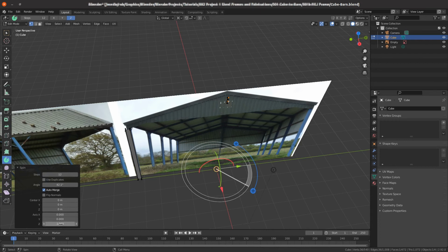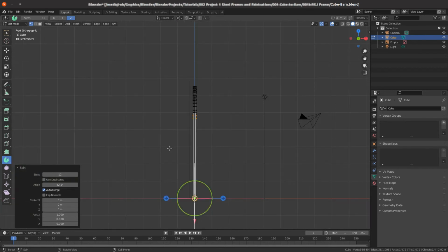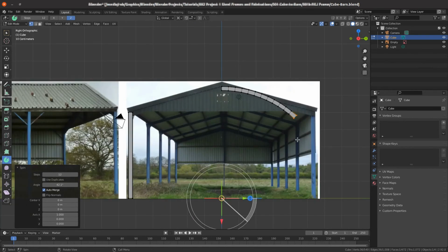At the moment Z is set as 1, so that takes all of the rotation, and we want X to be set to 1, so we'll set that to 1, and you'll see the shape change, and we'll set Z to 0 and go to numpad 3 so we can see what's happened. We need to go in the opposite direction with this, so you can put -1 in front of the axis, and we're starting to spin in the right direction, and we can spin further.